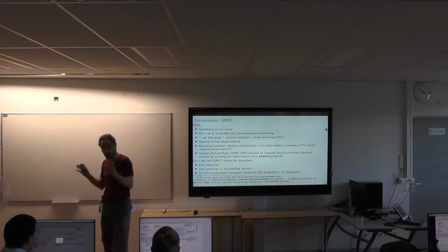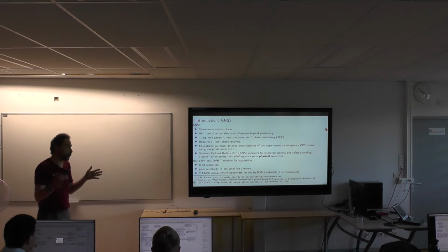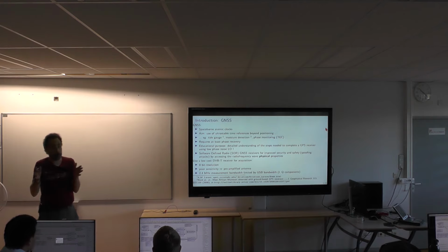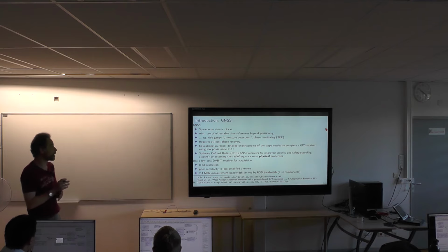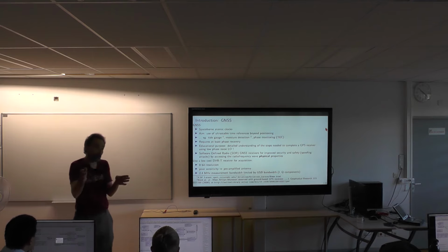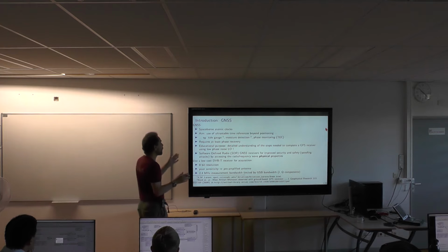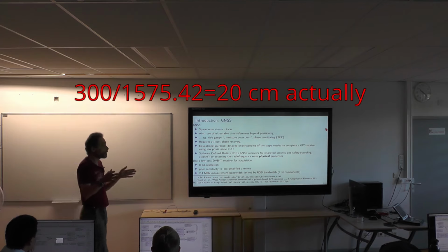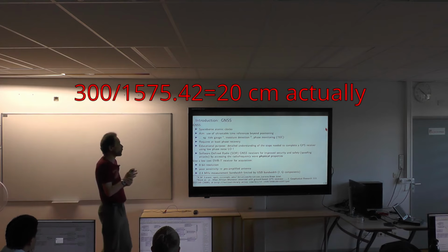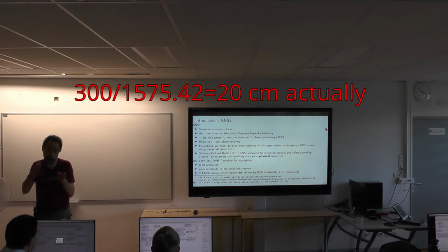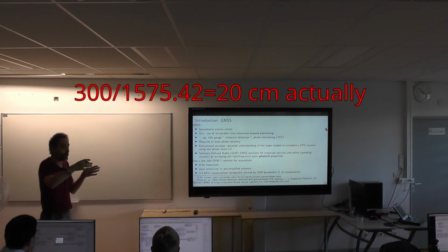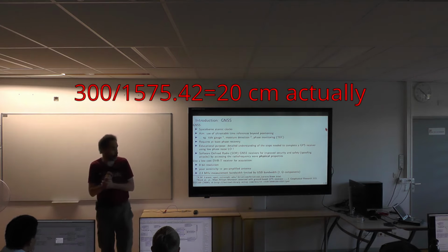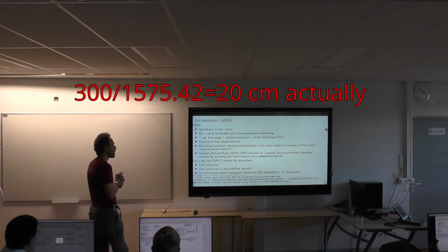Most of these techniques will require phase recovery, because we're going to see that the code broadcast by most of these GNSS signals is 1 megahertz, namely 1 microsecond between the messages, and 1 microsecond is the time needed for light to travel 300 meters. So the range resolution of a code is 300 meters, whereas the carrier at 1.57 gigahertz gives 15 centimeters. So you greatly improve your resolution, at the expense, of course, that if you're measuring the carrier, because all the cycles look similar to each other, you're working with an uncertainty of 1 wavelength. So phase recovery will allow you to greatly improve the resolution, but makes the processing somewhat more difficult.